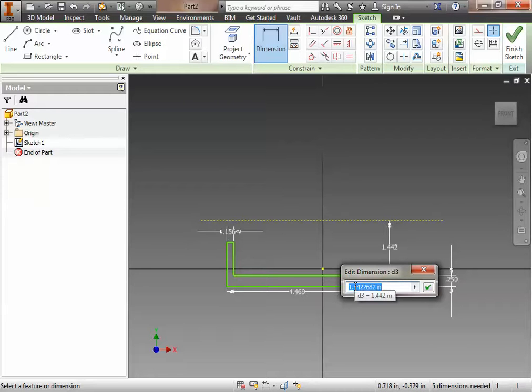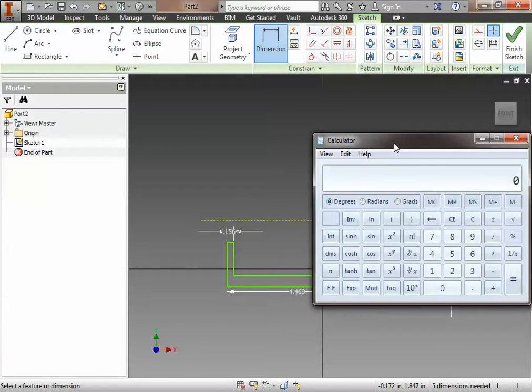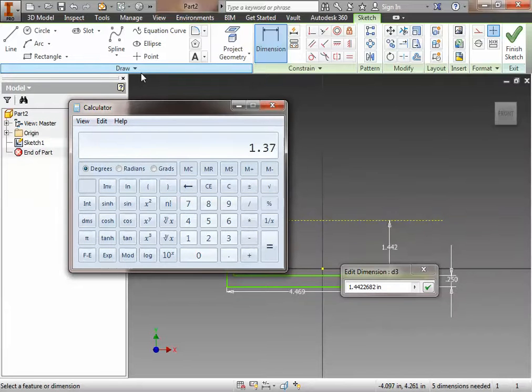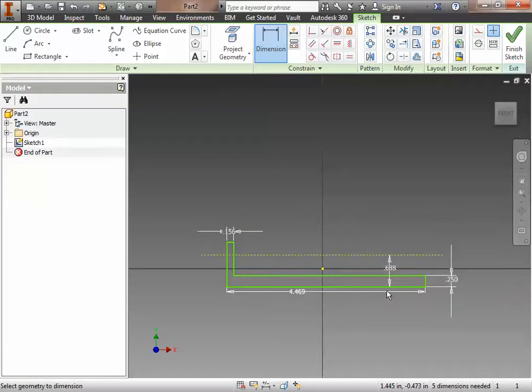And if I look at the drawing, it gives me the diameter. OD in the drawing, by the way, says outside diameter to specify that it's talking about the outside circle, not the inside circle. So 1.375 outside diameter, and if I want to find that radius, I just type in that diameter and divide it by 2. If I do that, I see that it's 0.6875, and again, don't be scared when you put this in. It's going to round it to 0.688, and that's okay. Now notice I moved my axis down, but don't worry about that, because the next thing we're going to put in is how far away this particular line is from here.